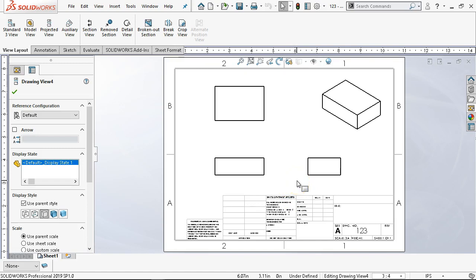All right. So once we have this part in place, now we can actually do tolerances. So my general process, and we'll go through this again, is if we are working in an assembly, and really, like I started off with, if it's just a block sitting on the table and it doesn't have to connect to anything, it doesn't require any fasteners, we're not even going to glue it to anything, then it can pretty much go without tolerances, unless it serves some specific function as a fixture or some portion of our tooling.